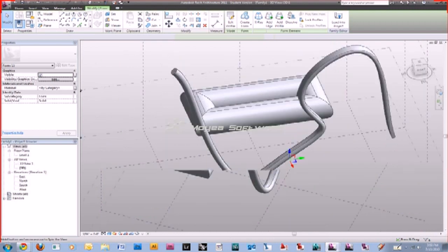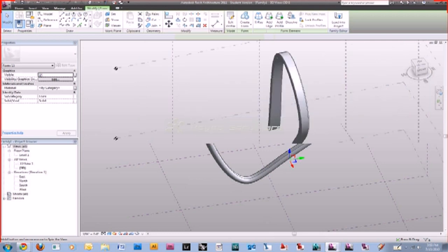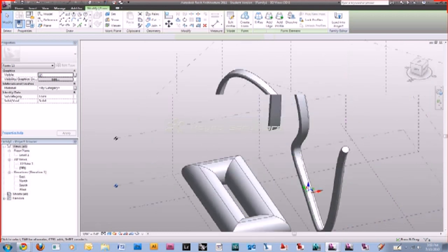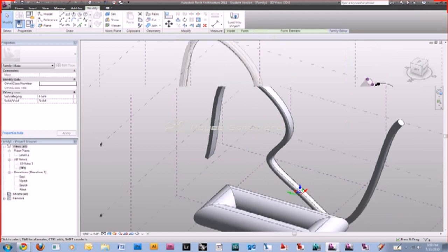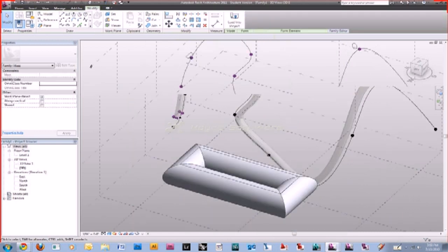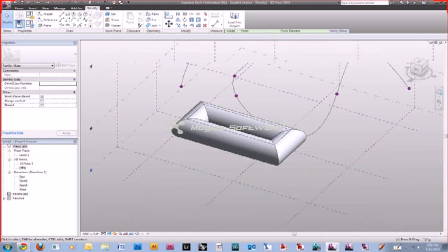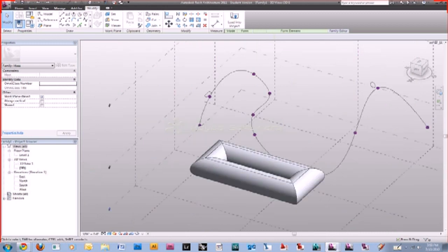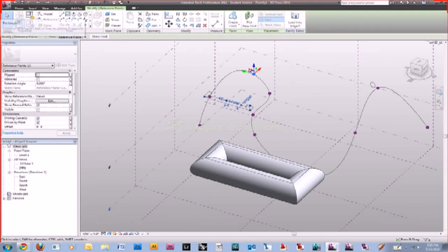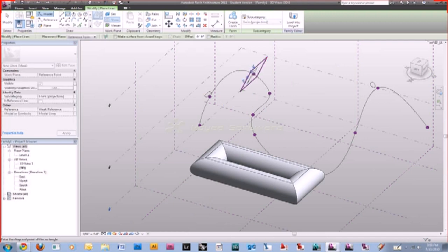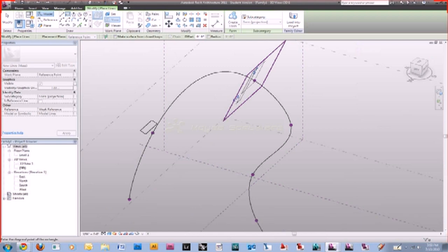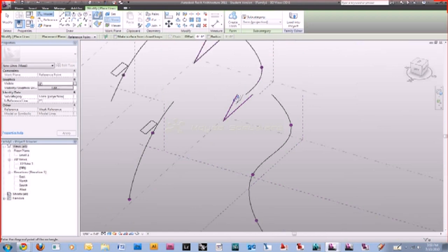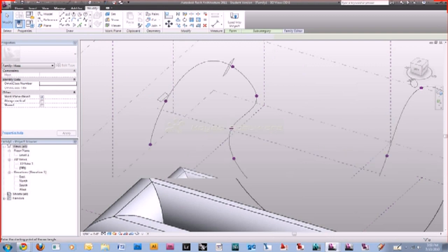All right, great. Another thing I didn't really explain is that I just turned a square into a circle. I probably can't even go back that far. Basically it's adding two tools together, because the tools aren't independent of each other. You're only using reference lines, profiles, and edges, and then you're creating a form from it. What he basically did was use the loft and the sweep all in one, combining those. You're not going to say, all right, use the loft tool, now use the sweep tool. That's kind of what you had to do in 2009 Revit, but not in 2011. In 2010, it was a disaster.